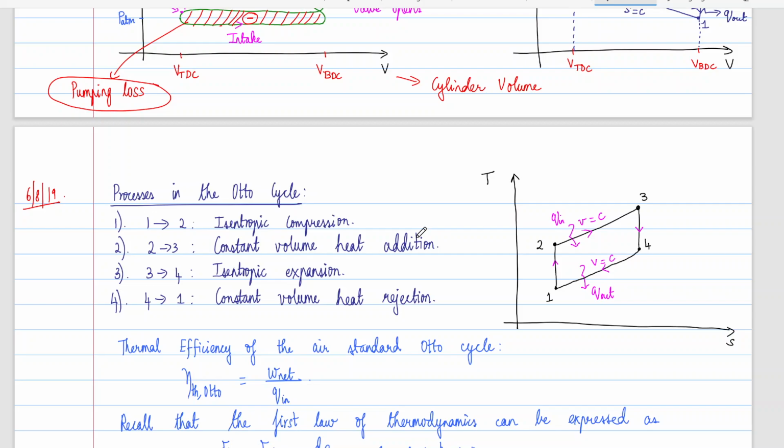One more doubt, sir. I had an idea, I don't know whether it is existing or not. With a shaft with a gear, can I mount that gear on the shaft with a bearing kind of thing between the gear and the shaft? Wait, you want the gear and shaft to be coupled together? No, you can't add a degree of freedom like a bearing there. If you add a bearing there, then the torque transmission won't happen, right?